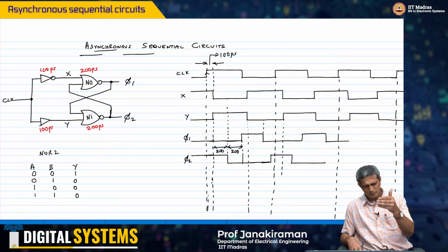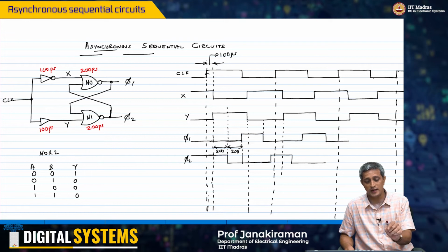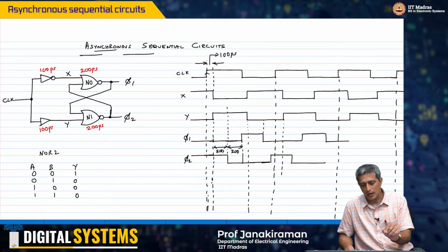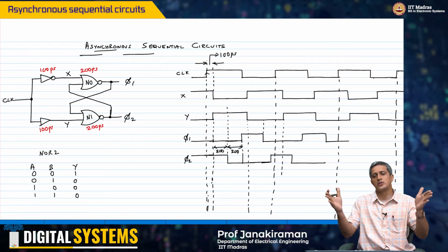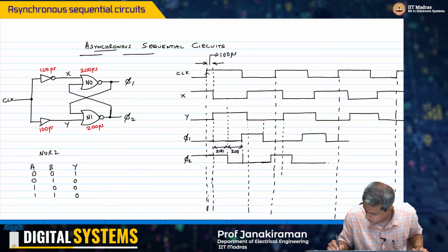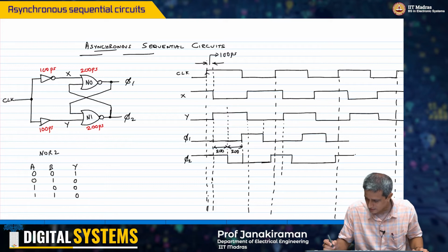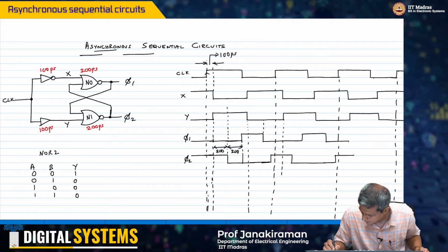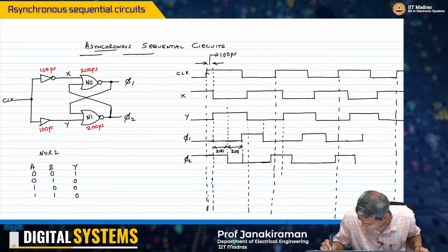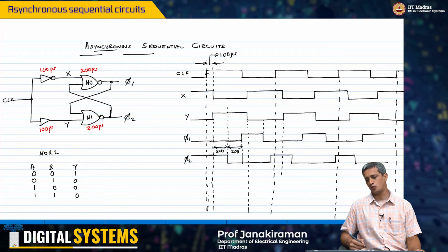So this is just one of the examples, right. By controlling the delay of n0 and n1, you can control this whole non-overlap period. And this whole thing will simply continue exactly like this, and give you a very nice non-overlapping clock period generation, phi 1 and phi 2, okay.